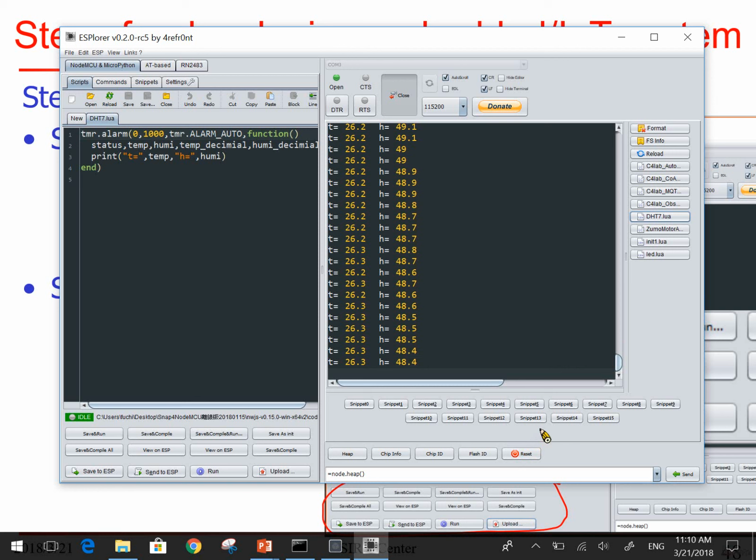The second thing is Arduino is only 8 bits, which makes it almost impossible to do some encryption and decryption to protect your data. However, a 32-bit processor has the power for encryption and decryption, so this chip is more fit for IoT, and Arduino is better for makers. If you want to do something fun, that's very fine. But if you want to do some industrial application, then Arduino might not be fit for that kind of application.